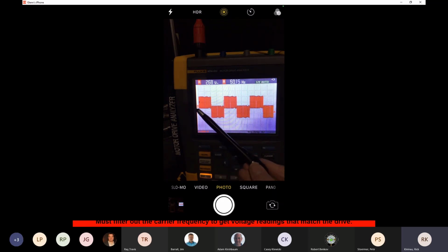If you look at this, I call this the envelope, the red smudges. Now the pulses are buried in there, but imagine a sine wave just kind of drawn here. That's what the motor's responding to. The motor doesn't have the bandwidth, or the motor cannot respond to the pulses. So it follows the envelope here, and I'm just going to slow the speed down.